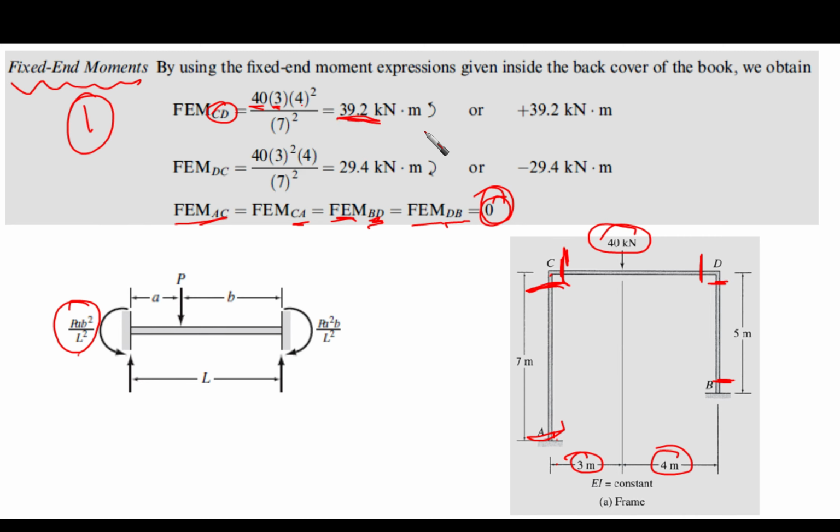Yes, the slope deflection equation is going to be applied at the three members, AC, BD, and CD. We're going to apply it 2 times at each end. So for example, for AC, we're going to apply it here at A and at C. So we have moment MAC and moment MCA. And then we are going to apply equation 16.19. From where is this equation? It is from the previous video. Please revisit it and you are going to understand what I'm talking about.